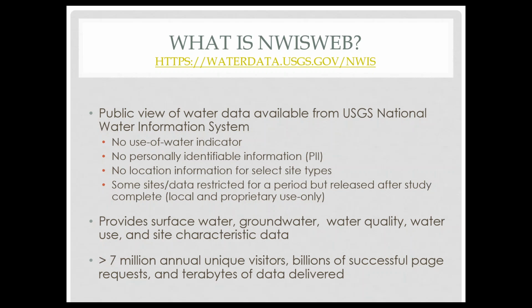Otherwise, when I take a water level, I may not get an accurate water level that represents the aquifer system. If the well is at an angle or not well constructed, or the screen is not open, all those things you need to know before you include existing wells in your study.